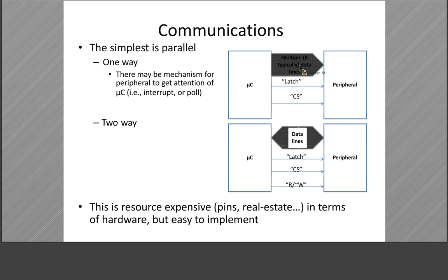Here we see a data bus from, for example, master side, microcontroller side, to a slave side, to peripheral side. This direction is from master to a slave. It is a parallel bus, for example, 8 bits or so. And these two pins are for control, for handshaking.